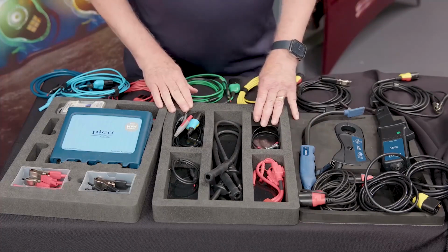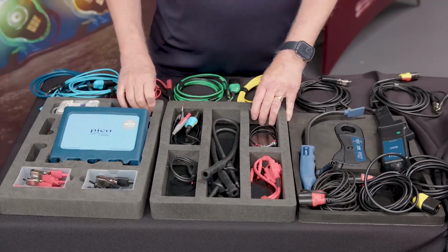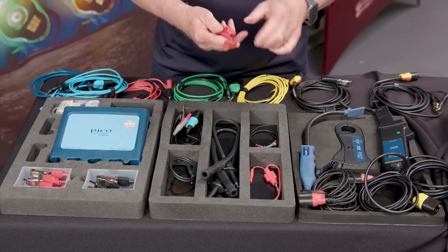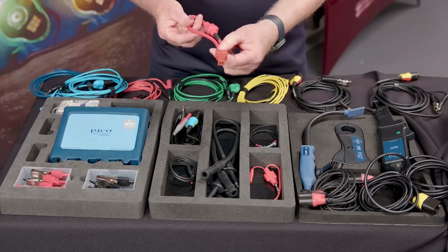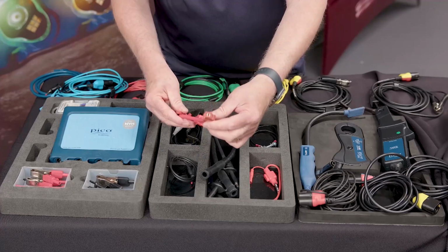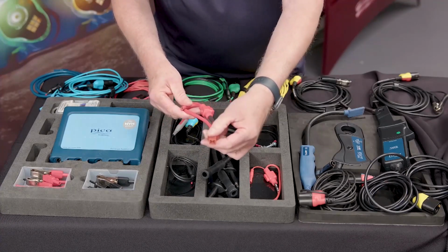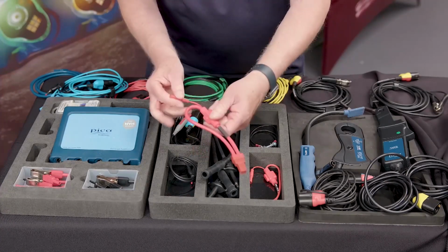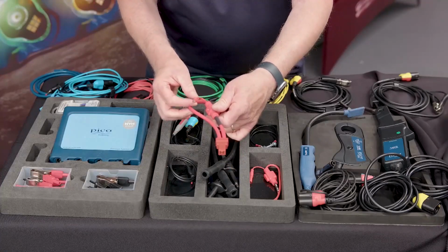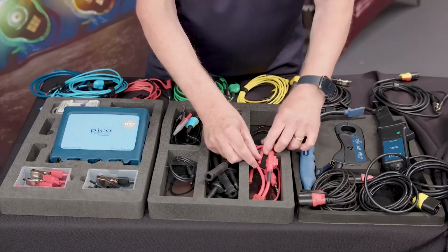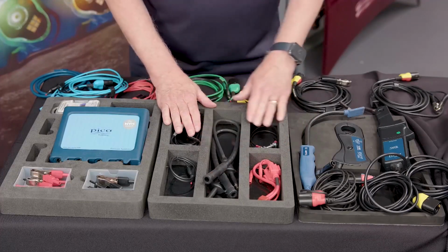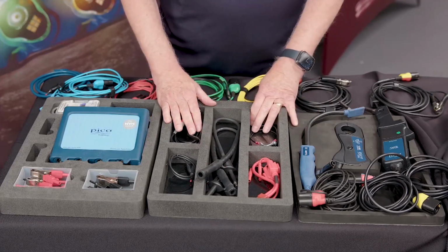So one of the main problems that we have, like anything, is always connecting to vehicles. So not forgetting that we have a selection of different fuse extensions, which again, we can take the fuse out of the fuse box, plug that in there, put it into there, and we put the current clamp round there. And we have a little voltage takeoff as well. So these come in numerous different sizes. Very, very good for making connection to components in circuits.